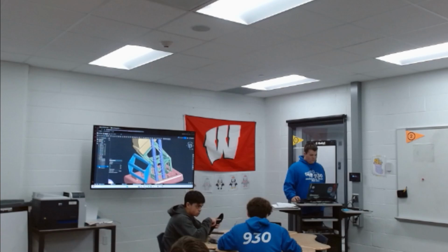Is that how it works? So with the mate connectors, when you choose a fasten, that's saying these two mate connectors are stuck together. So it's constraining in every direction. So he chose the center of the back, and he also chose the right center of the two back. So it aligned them together.